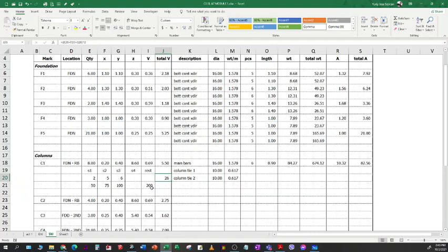And then for the rest, before we can compute the rest, we still have to add all of the spacings accumulated near the support. So if we add all the spacings, let me use this cell here, 2 times 50 plus 5 times 75 plus 6 times 100. No, sorry. We link it here. Plus this one, S4, times the lower part, which is here.